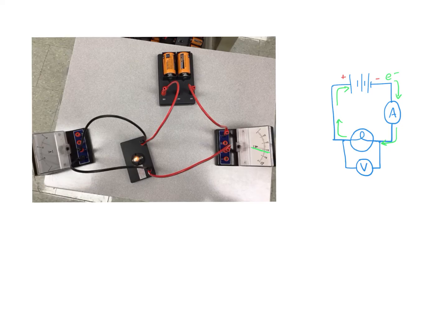So that energy gets transformed from electrical energy into the light energy predominantly, and in doing so, those electrons have lost energy. So when they come out on this side, we still have the same number of electrons, but now they don't have the same energy they had before. The voltmeter is picking up the difference. How much did the voltage drop? How much did the energy of the electron change from this point to this point?